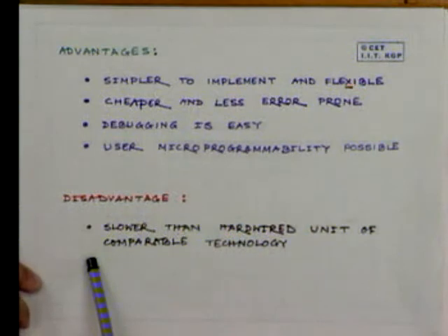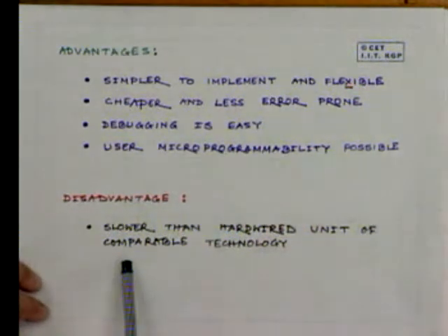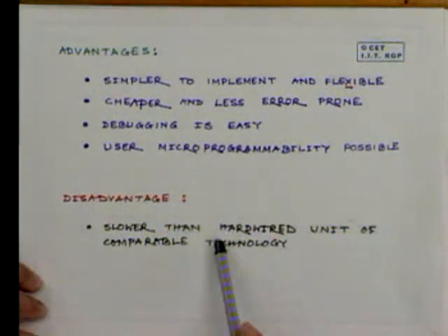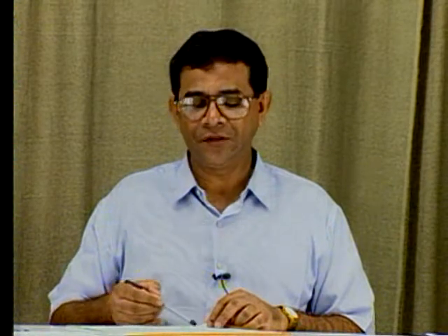Now here you see, as I said earlier, if you have simpler addressing modes and a simpler instruction set, then you can have simpler hardware, and in that case you can go for a hardware control. Otherwise, if it is complex, one tends to go to a microprogram control unit.